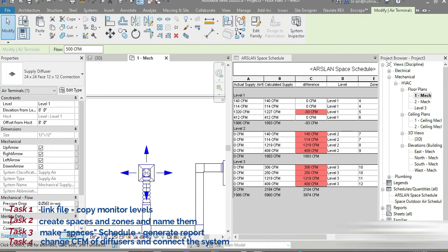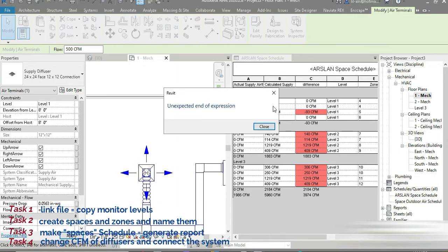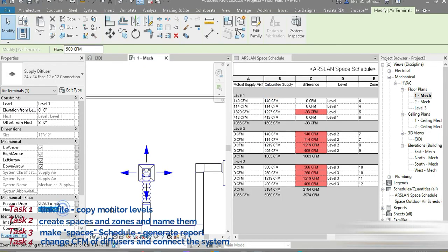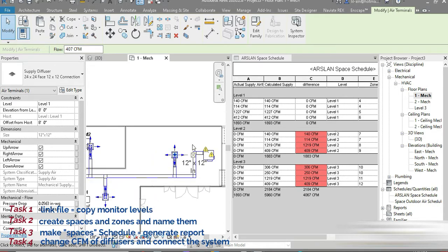And guys, another extremely cool feature of Revit, you have a calculator within every field. So equal, so it's 1227, right? Now check this out. How about we press equal 1227 minus 410 minus 410 for the other two, and a 407, and that warning got removed, guys. Look at how awesome Revit is.